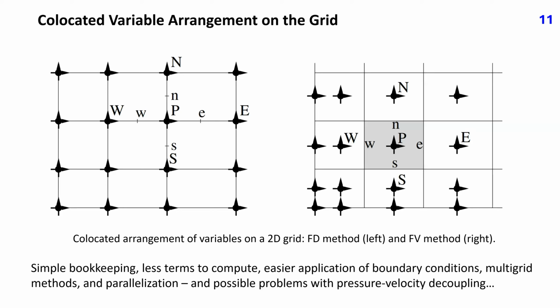operation. The only disadvantage of this arrangement is that decoupling between velocities and pressure may occur unless special precautions are implemented, which is manifested in checkerboard oscillations. This will be addressed in lecture 18.